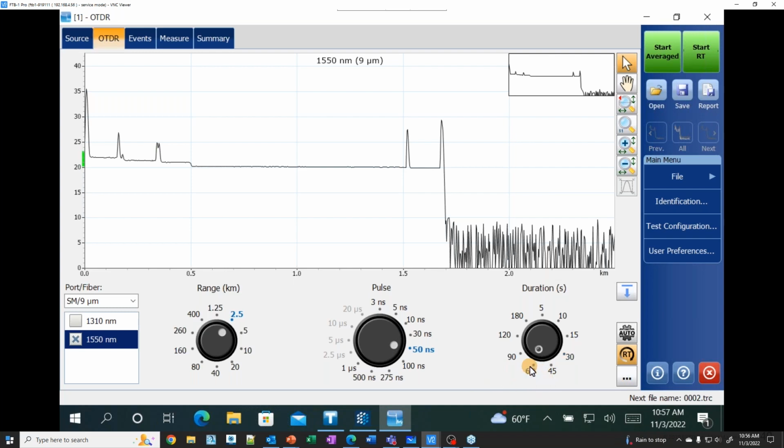The longer the duration, the more information you get, the better the resolution, at the expense of time. I'd rather test 60 seconds and get the 4 events than test 10 seconds and only get 3. If I'm doing high count, then I might reduce the duration as long as I don't affect the quality of my results by merging information.